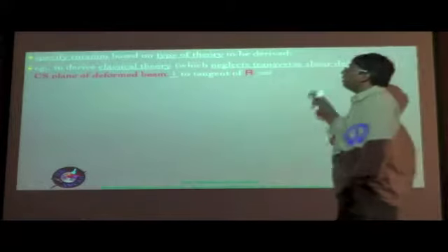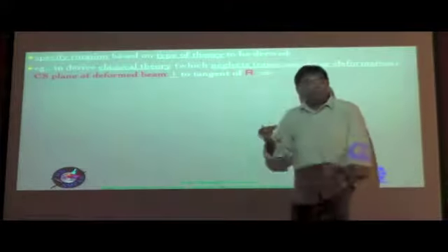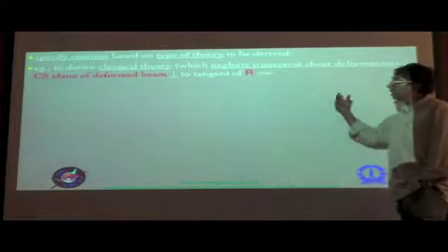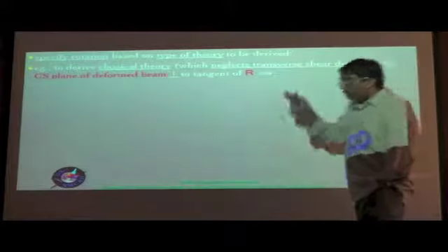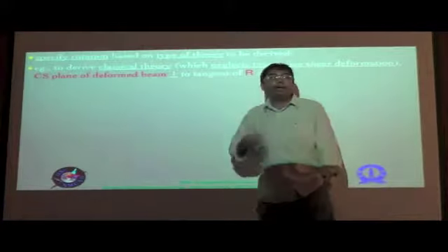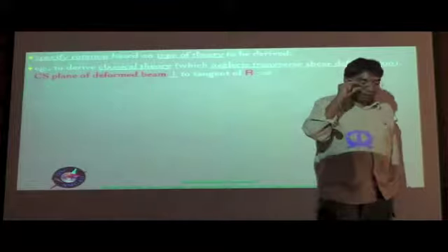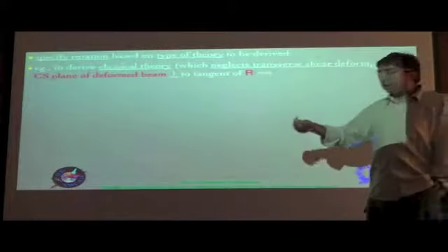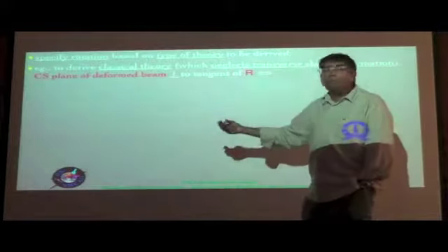Now we specify the rotation based on the type of theory to be derived. That is, either we're talking about the small local rotation theory or the medium, moderate local rotation theory, etc. Here we are focusing, of course, on the classical beam and a very simplistic example of only planar deformation. The first thing we do is derive the classical theory, and in fact that would be the case even when you're considering a more complex, general example.